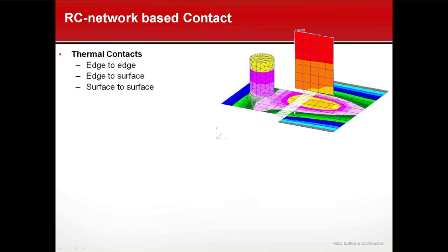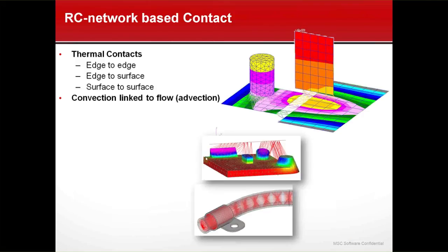And if you can see these small little lines here, these little bar conductors, these are automatically added by our software. All you specify is that you want that edge hooked to that edge, or that surface projected down onto that surface, and it will look at your meshes and hook up the right conduction for you. And we do that in a fairly sophisticated fashion and do it as accurately mathematically as possible, even though the meshes may not line up.